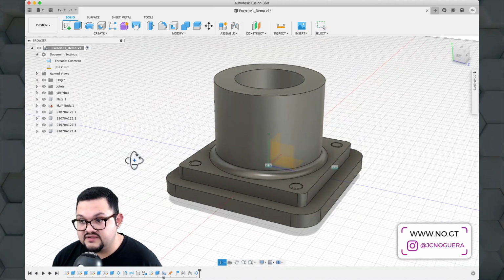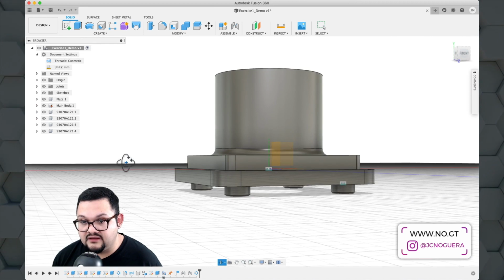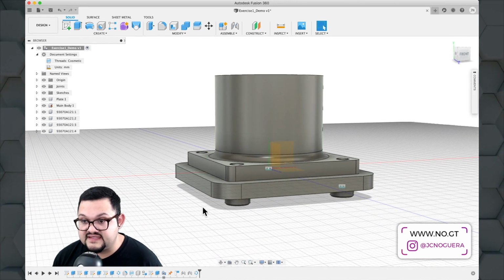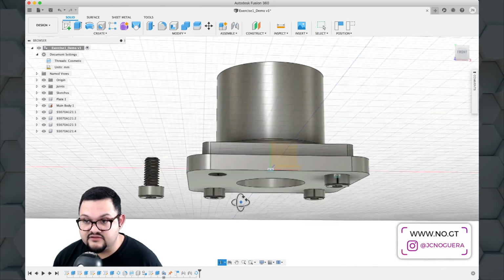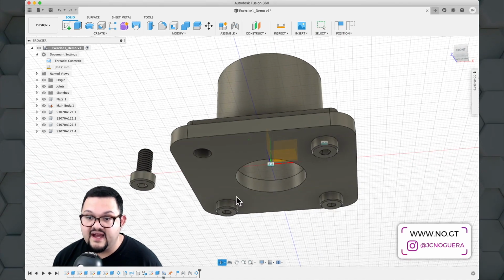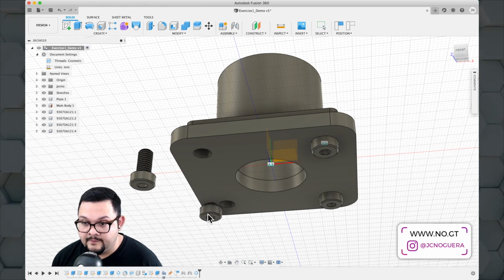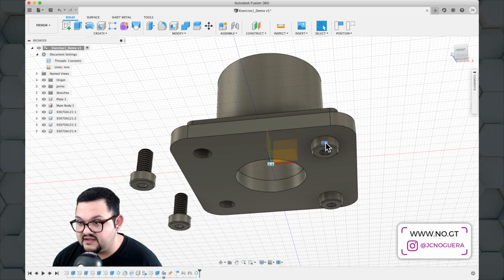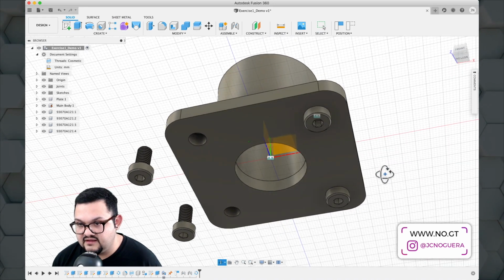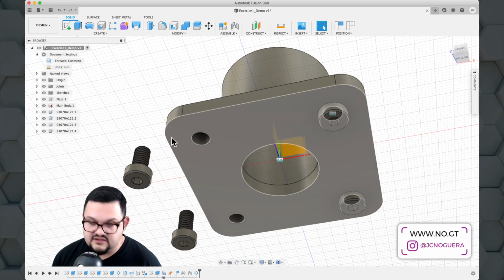Also take into account that anything that you copy along is not going to carry the assembly. The joint for this is not going to get copied. So I can see these copies that I've created, I can still drag them around. They're not fixed in place. I still have to assemble these in place. And you can definitely tell that happening because I have this joint there that is visible that is not visible in the others. So I can go back and again do joint.